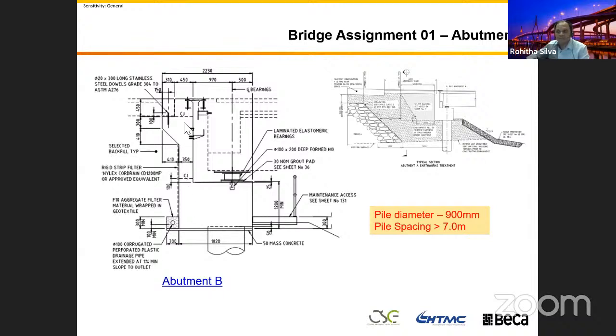If you go to the top, you will have issues with getting this bracket and support and this one in here. This 350 you can reduce to 300, but you can't reduce to 250. If you reduce to 250, you can't put your vibrator inside to vibrate the concrete.